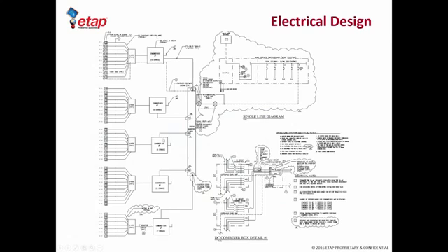Ideally, you would like this to be balanced as far as possible, but we can see that we have a little bit more room to grow here in combiner box number 7 if you want to expand further into the remaining car spaces. The combiners essentially end up going into the inverter, which is shown here with this rectangle.